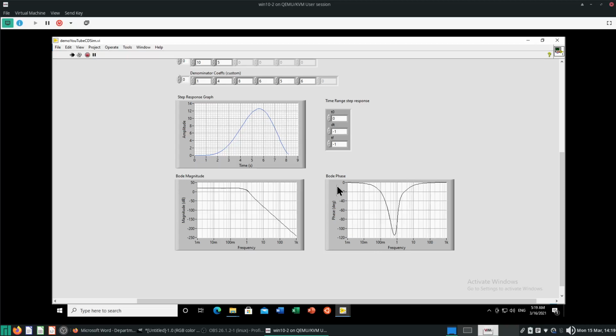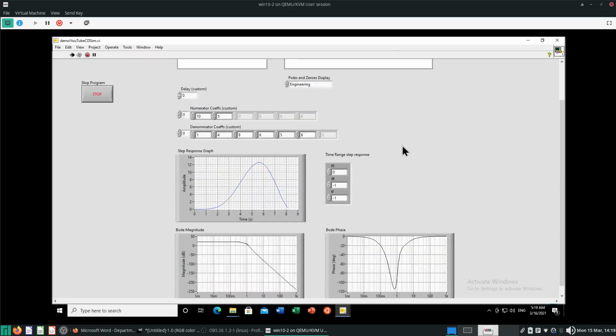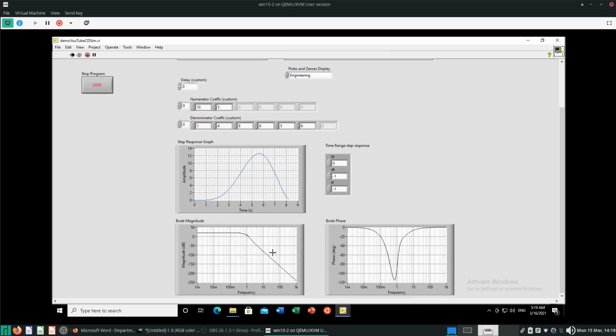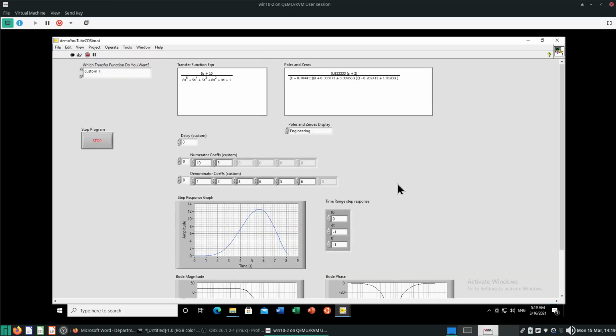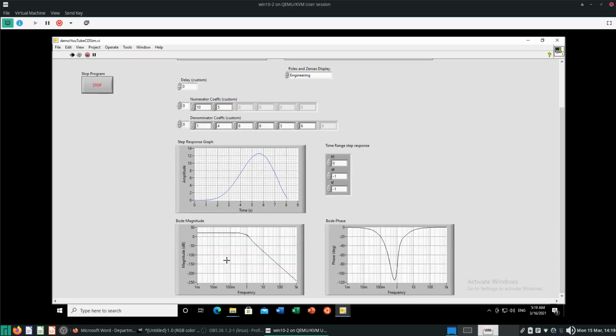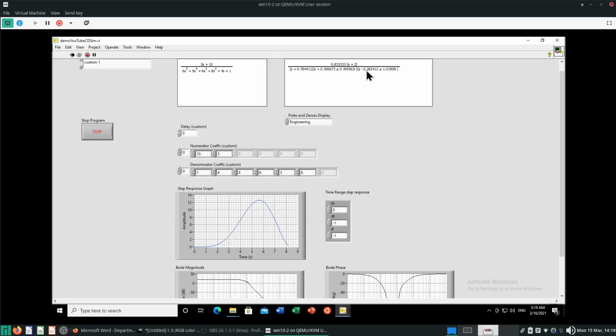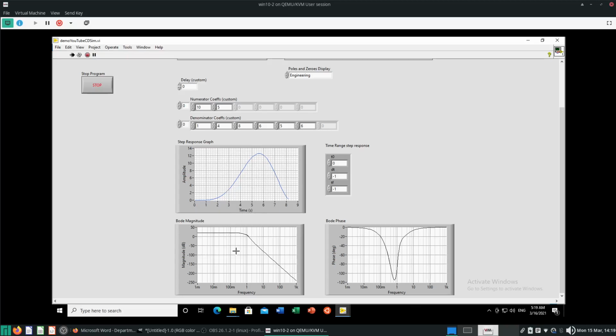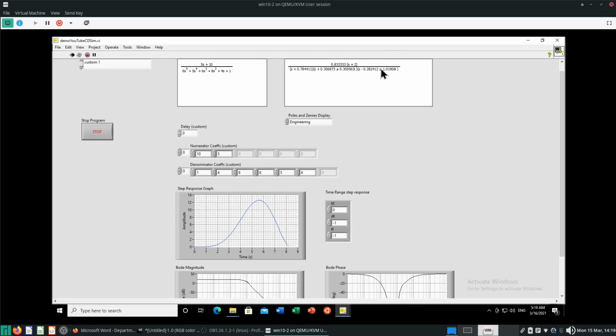So the phase plots and magnitude plots are as follows. Of course, you can't quite see that it's an unstable system from these Bode magnitude plots. Ideally, if there's a pure real pole on the right hand side, you will be able to see, if you increase the frequency to a certain range, the magnitude going infinitely up. Unfortunately, we don't have pure real poles here, so you can't really do something like that.